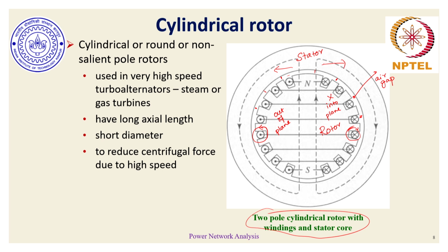And if I were to add or superimpose all these fluxes, essentially it would mean that the effective flux, because of this rotor current in the rotor core, is leaking out or moving out of the rotor core in the upward direction, and the same flux lines, since they are closed lines, are entering the core in the downward direction. Now remember, in physical magnets, flux lines always originate from the north pole outside the magnet, and they enter the magnet at the south pole on the outside, whereas inside the magnet the flux lines originate from the south pole and terminate at the north pole.